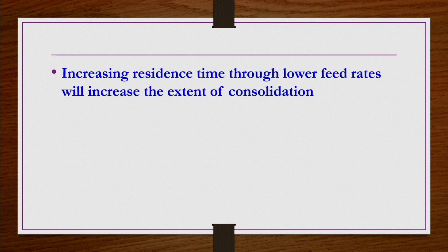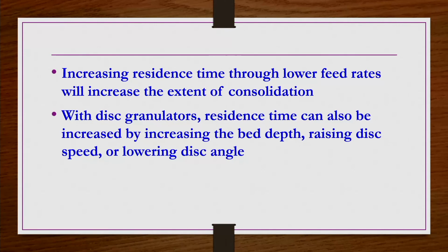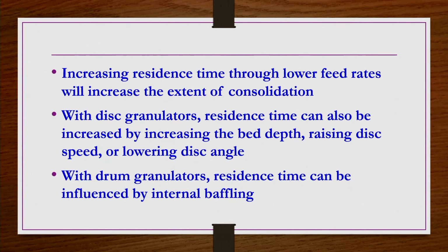Further, increasing time through lower feed rates will increase the extent of consolidation. In the case of disc granulators, residence time can also be increased by increasing the bed depth, raising disc speed, or lowering the disc angle. In the case of drum granulators, residence time can be influenced by internal baffling.